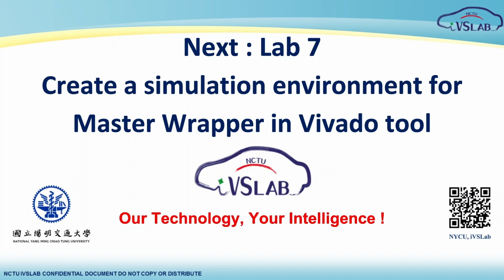The master wrapper will initiate a write request to store data, read it back from the exact same address, and perform an automated data integrity check. This allows us to rigorously verify our master logic and address mapping.